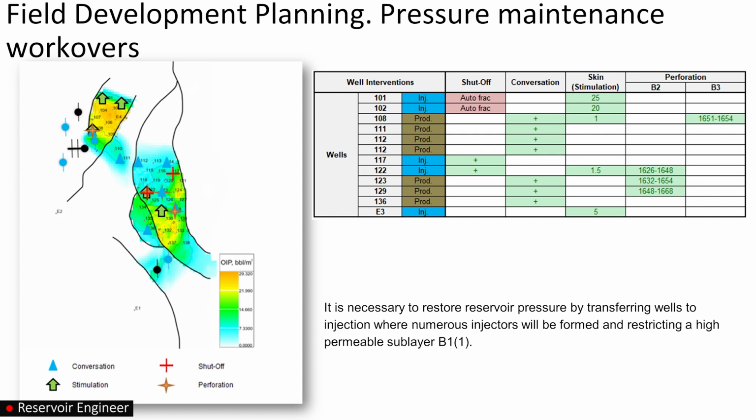Regarding the northern dome, as I understand, the zone around wells 110, 111, which works for the formation B1, is connected to the formation B3 of the main northern section. I suggest either transferring 111 into an injector or well 110 to compensate formation B2. We can also perform a reservoir flow profile on inactive well 108. Based on the result, plan relative workovers and transfer it into injection.